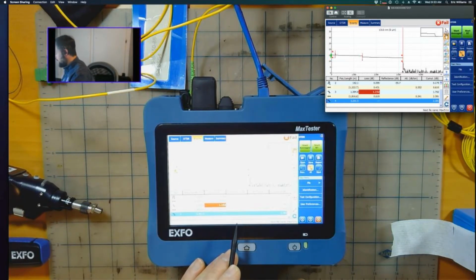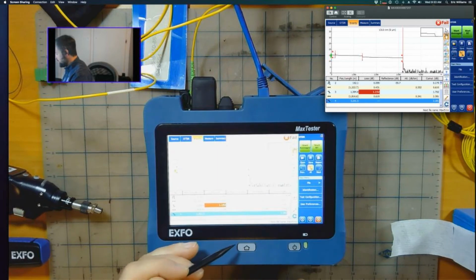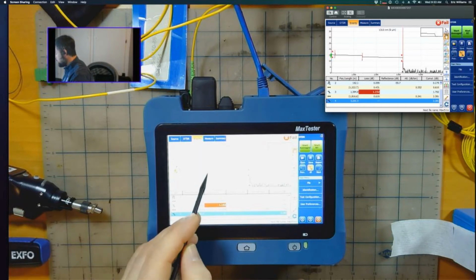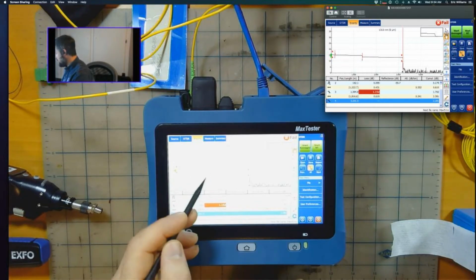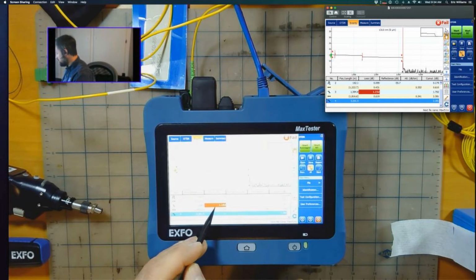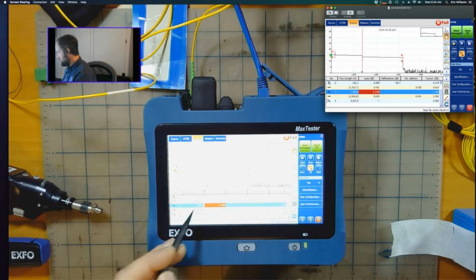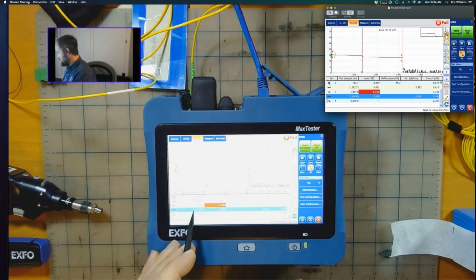The thing that I wanted to point out with the OTDR here is even in auto mode, which is what I see a lot of customers use, I do see from the launch cable out roughly to the first splice, I would consider it a fail. It's got a loss of 1.152, which is about in line with what my PON environment tells me it should be. No reflection on this, so I can tell that it is a splice, or I can make the assumption that it's a splice. And then I have another about 1,800 meters in this case before I hit my splitter.